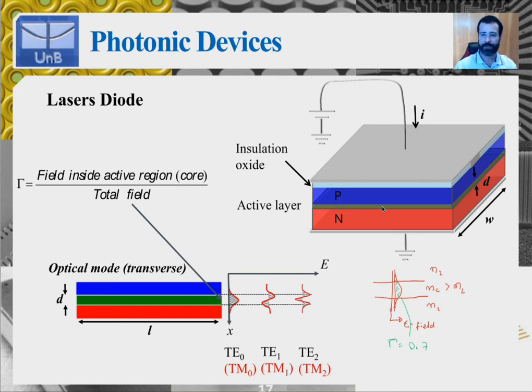and for optical wavelengths the cavity is going to support many modes, many longitudinal modes. So even if you design the waveguide, the active region, the thickness and the width, to support only one transverse mode, the cavity itself will have many modes, because it's a pretty long cavity.